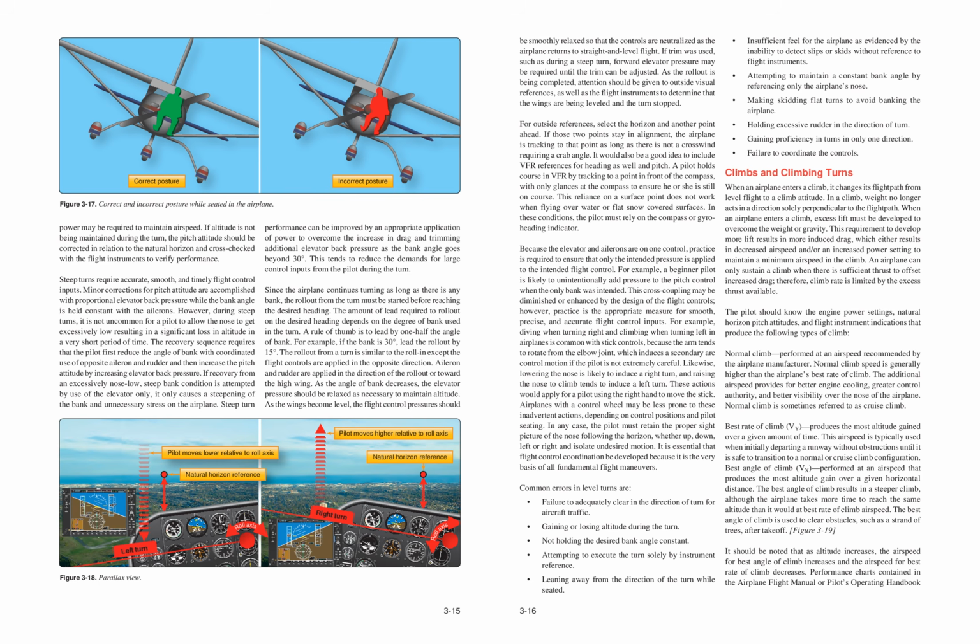Climbs and climbing turns. When an airplane enters a climb, it changes its flight path from level flight to a climb attitude. In a climb, weight no longer acts in a direction solely perpendicular to the flight path. When an airplane enters a climb, excess lift must be developed to overcome the weight or gravity. This requirement to develop more lift results in more induced drag, which results in decreased airspeed and/or an increased power setting to maintain a minimum airspeed in the climb.